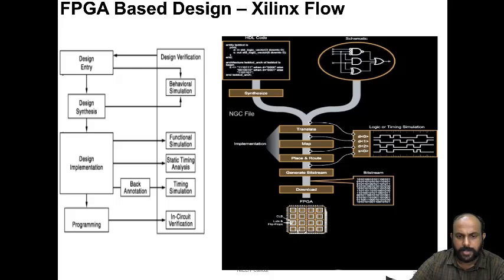The synthesis produces a particular file format. In Xilinx terminology, it is called a native generated circuit file, or NGC file, which is again subjected to a lot of logic or timing simulations. At each step of implementation, like translate, map, place and route, some kind of simulations are run so that the design is verified. For example, functional simulations are done, layout versus schematic checks are done, then static timing analysis is done. If there are any timing violations, they get back-annotated to the design implementation stage, where they